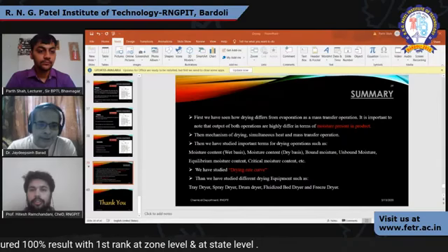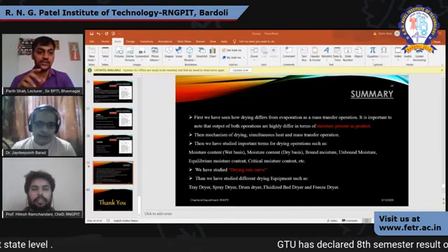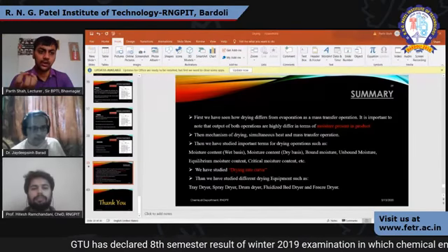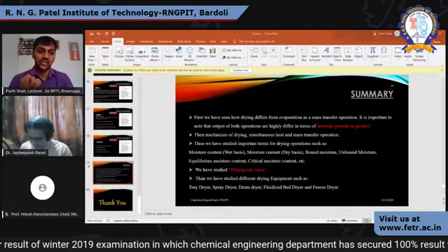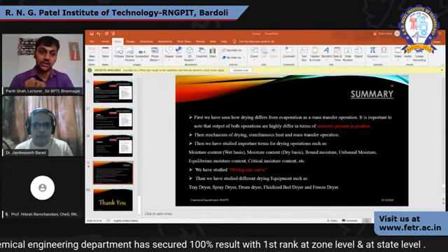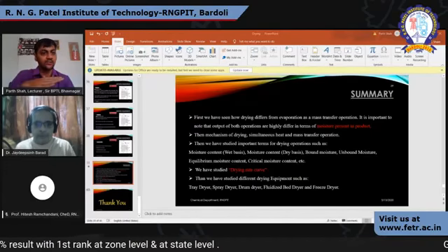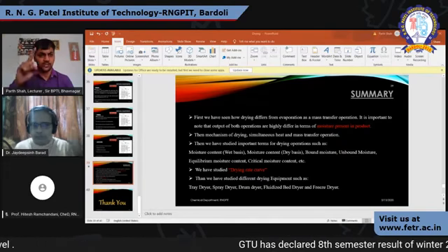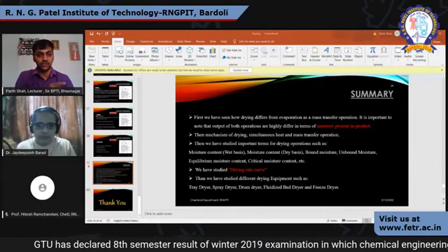What is hysteresis in drying? What happens is that when moisture is absorbed in a wet solid, the solid is capturing the moisture, so moisture is absorbing inside the material. Initially the moisture content is increasing, but when we are doing drying, there is a decrease in the moisture content.